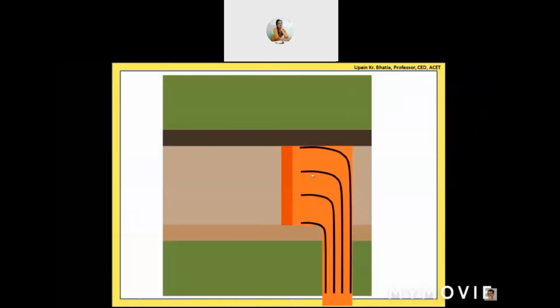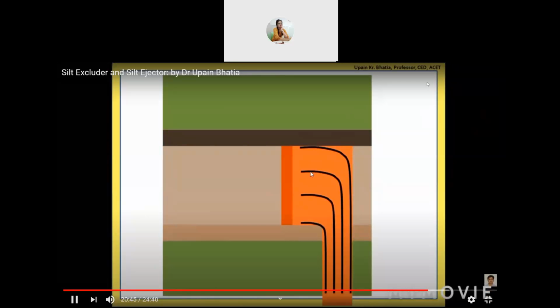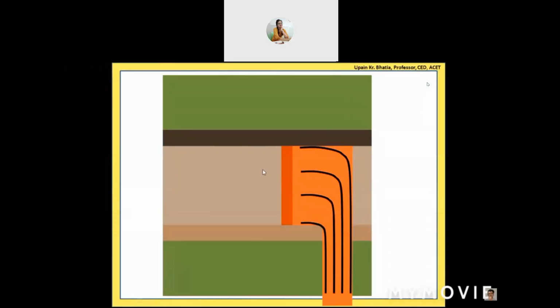So they are low height walls, very thin walls, and the top level of these walls is a little above the canal bed level. Okay, a little above the canal bed level. So what you see is here the gap between the walls is very high. Here the gap between these walls is low. We can provide these intermediate walls also, which may not run up to this end, but they are provided in intermediate position and they run up to these points only, here, here, and here.